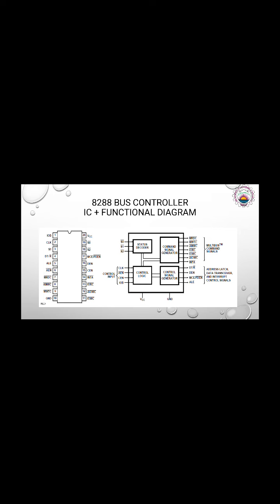So these signals were present on the package of the microprocessor in minimum mode. But in maximum mode, some of the maximum mode operation signals replace these signals from the package of the microprocessor. So by using the bus controller, we have regenerated these important signals to be used in interfacing of memory and I/O.